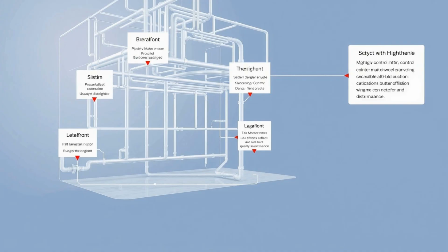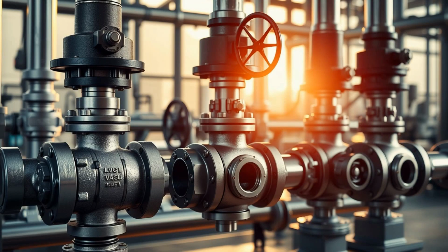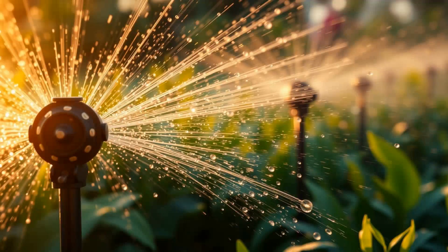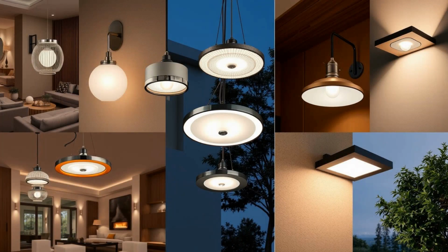and maintenance. Valves, especially the main control valve and zone valves, are critical for isolating parts of the system and ensuring manual operation if needed. Alarm valves are integrated to send electronic signals when flow is detected, simultaneously alerting occupants and the fire department. The true heroes, however, are the sprinkler heads. These come in different designs including upright, pendant, sidewall, and concealed types, each suited to a specific architectural layout.